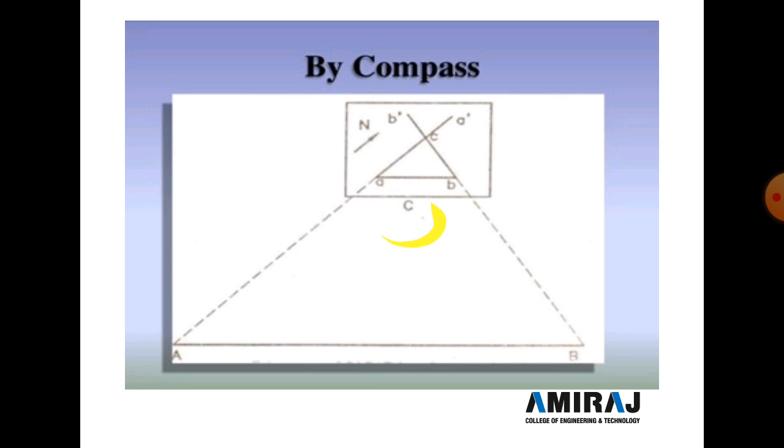Set the table at point C and orient it with the compass, then clamp the table.